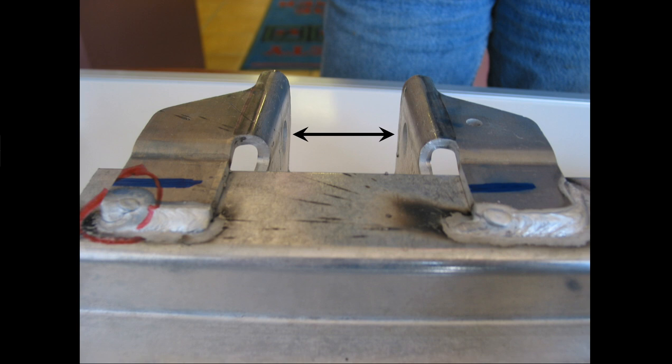We need local heat on a particular spot, and we need heat without wire coming, so we can blend these welds together a little bit. Once you become proficient at gas tungsten arc welding, you can terminate these in such a way that they won't require any more buffing or any nonsense like that afterward. You will be done.